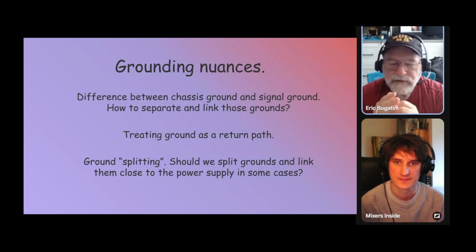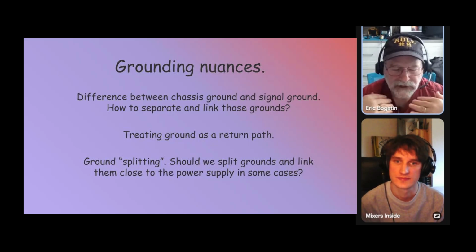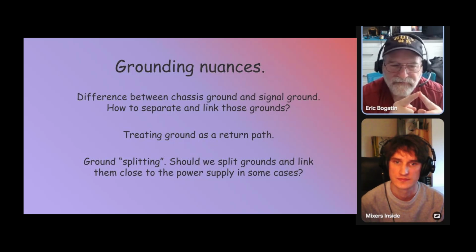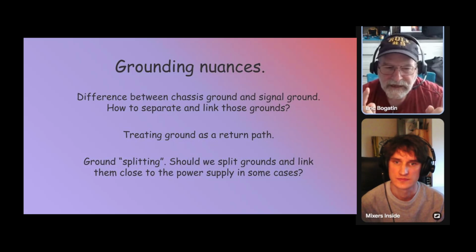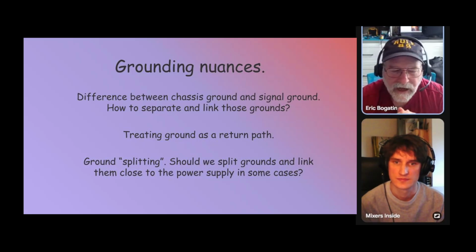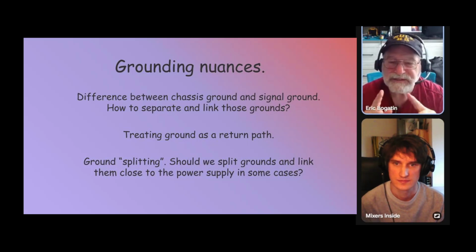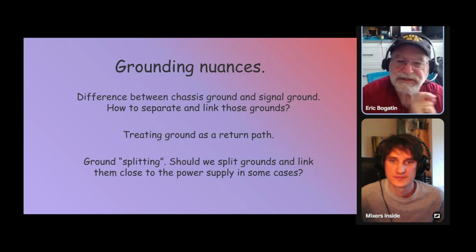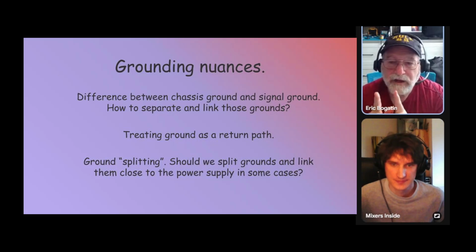There's no voltage drop in it, but it's still connected to the local circuit board ground. In different layout tools, it's sometimes difficult to separate out that net that you want as the very isolated reference, to separate that from the circuit ground that's node 0 on the board. And so one of the tricks that I sometimes do is I will use a 0 ohm resistor at the amplifier to isolate the trace so it's a separate node. So the net name for that trace is return for sensor 1. Yeah. Because it's connected through a component to local ground at the amplifier.